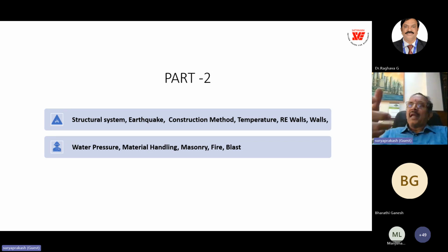So at the plant, they had given the dosage required for 3 hours, anticipating some delay in the transit, and the driver poured it all, like we suppose we are given antibiotics for 3 days. You take three days' dosage in one go, thinking that your fever will go fast. The same way, the driver would have thought, layman thinking, and having poured the retarder, the concrete never set.